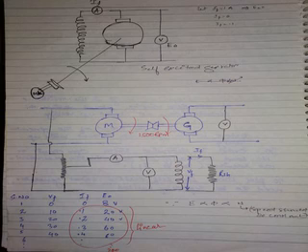if you say this is the maximum limit the machine can build up for this value of resistance, for above the resistance value, above critical. What is this value? Residual voltage, 6 to 8 volts.